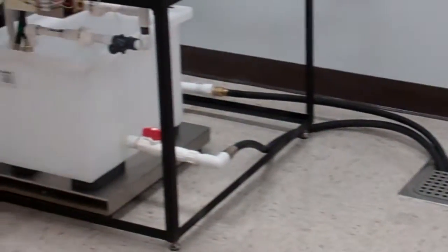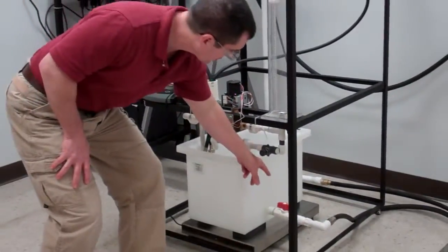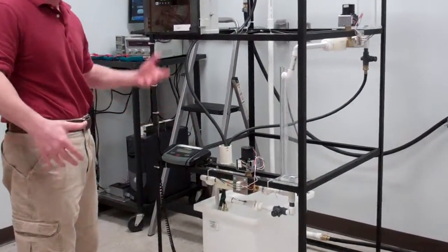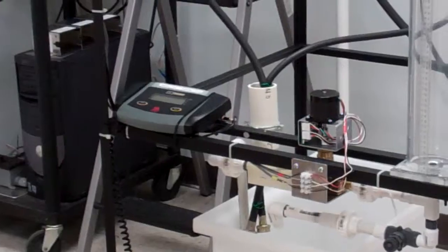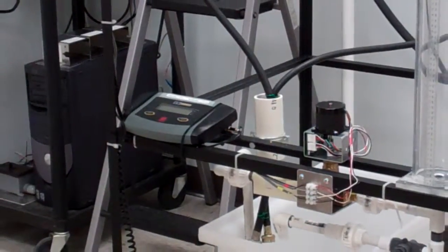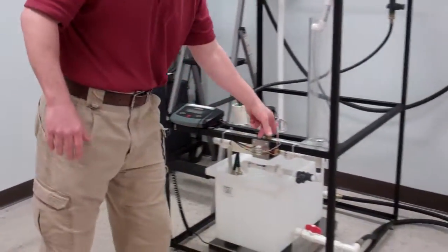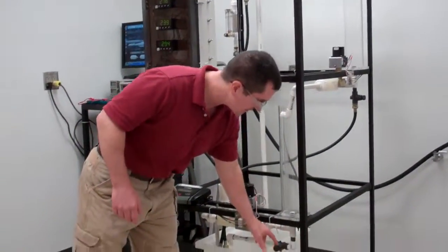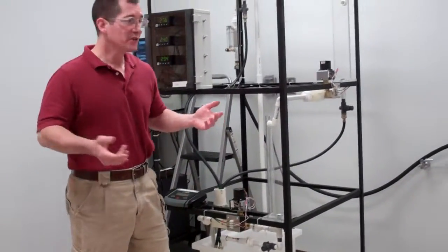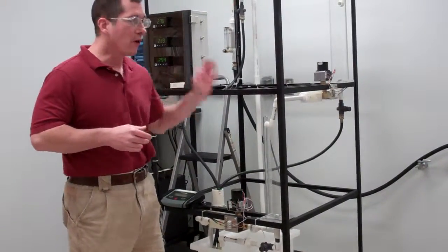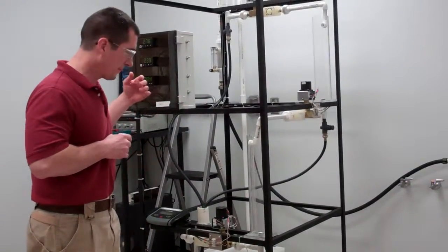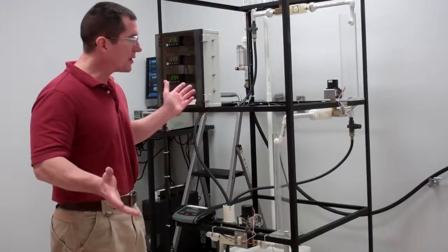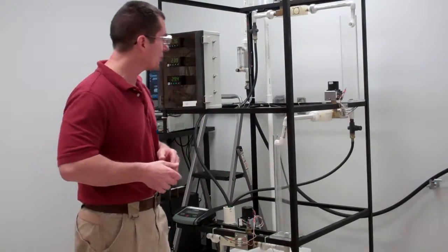And so all you have to do, just like on the Osborne Minerals demo, is close the discharge valve and watch the scale increase in mass. When it gets to a convenient point, you start timing. When it gets to another convenient point after a minute, 2 minutes, whatever, you stop timing, and then open the drain valve to let it go to the floor drain. But the other purpose of these valves can also be a disturbance variable. Now we're going to use this apparatus for all 3 experiments: process measurement, process dynamics, and process control. So let me go ahead and start this thing up so you can see how it all works.